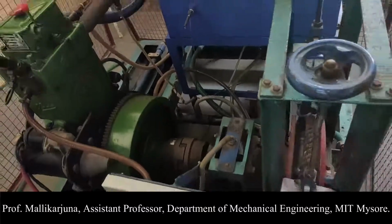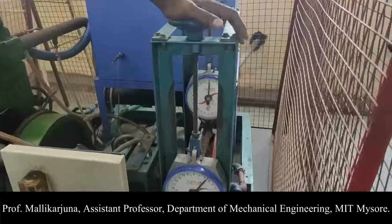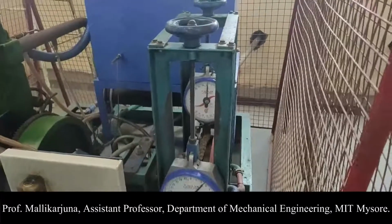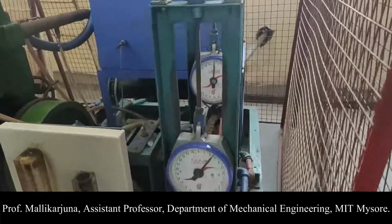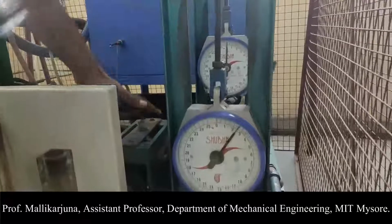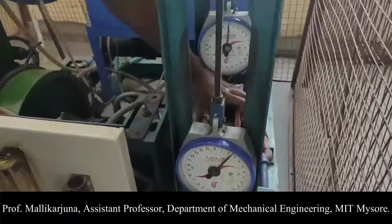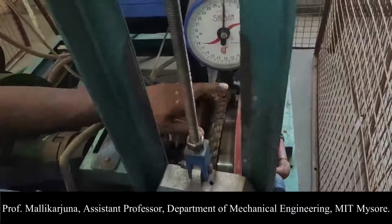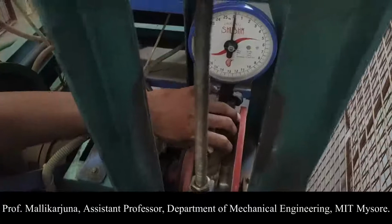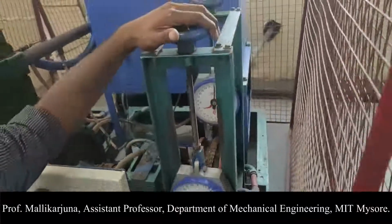In order to look into the performance of the engine, we need to load the engine. It will be loaded in an incremental or decremental order. This device is connected to the engine's crankshaft. Here we have the brake drum through which the load will be applied. The brake drum is wound with the help of a rope, and this rope will be tightened on either side.